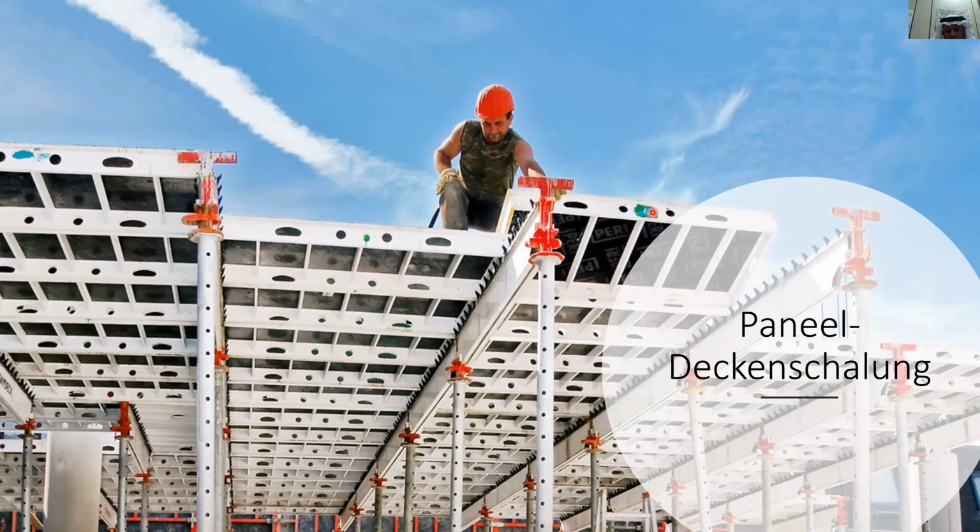And the support columns here, you see this red top, this goes up right to the top where the concrete will be poured on top. So there's a direct connection to the top of this column. So this column can and will remain in place after removing of these panels. So you can get rid of all the expensive material. You can use it somewhere else in the structure, but the support columns will remain in place.